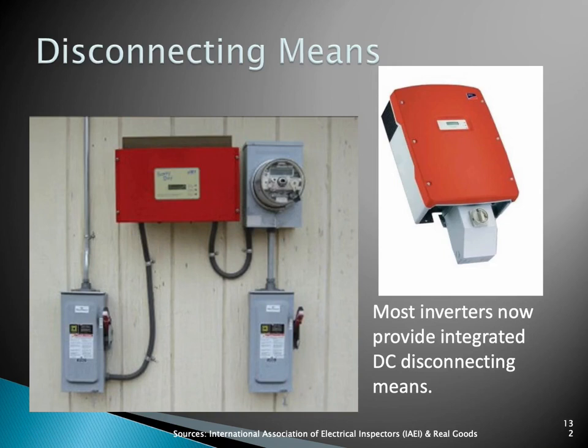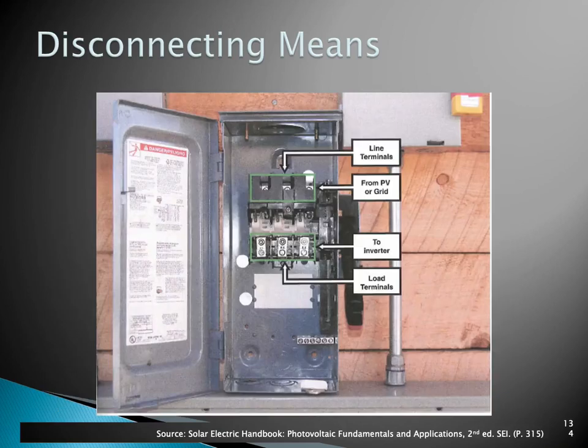It's either a knife connection, or there may be three conductors I may have to re-land, but it's not a big deal. I don't have to rewire everything into the inverter. But we are required to have this AC disconnect, which is going to be on the outside of the building.